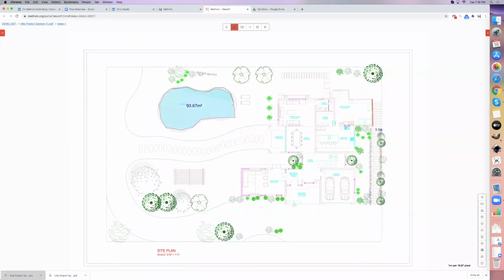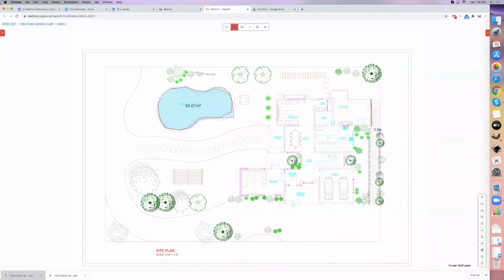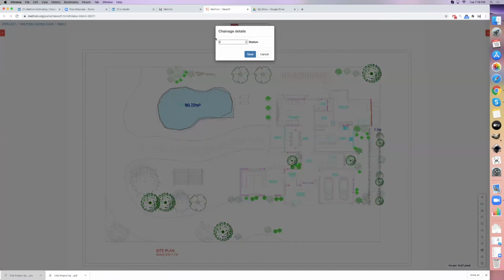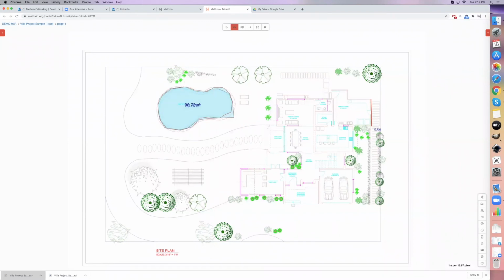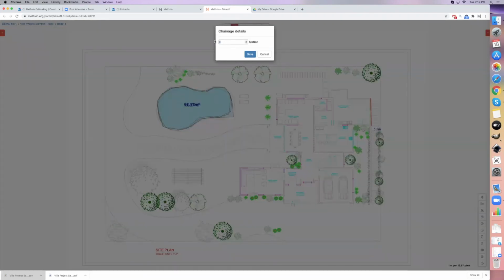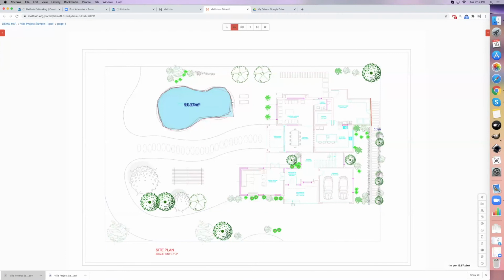But this is for a quick earthworks if you don't have the more expensive AutoCAD and things like that to use. So you can use this in cross-sectional, you know, where running along the road, where every 20 meters they give you a cross-section through the road. You can use this software to calculate your cut to fill on smaller jobs. If it was a big job, I wouldn't be using this. And what it'll do is throw the measure down here. So there's the fill. It's 183 cubic meters of cut that we need to do for the swimming pool.